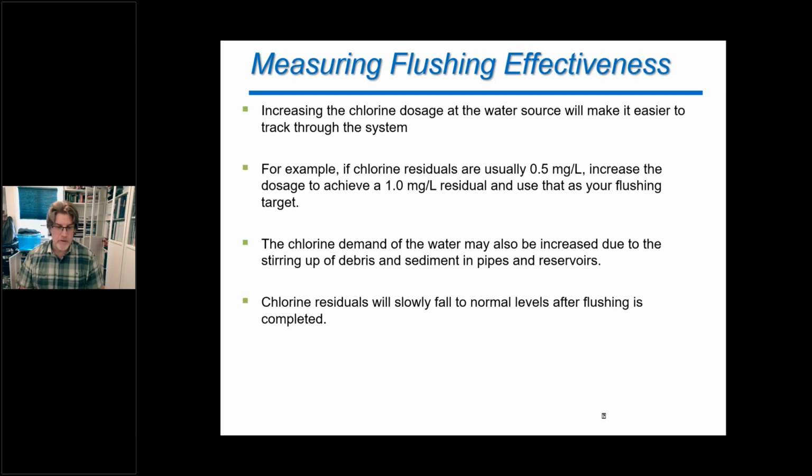And that's information you can put out to the consumers, saying, hey, while the flushing is happening, you're going to see a brief increase in the chlorine residual. And don't worry, after the flushing is done, you can turn the chlorine pump back to what it normally is set at. And that chlorine residual out in the system will slowly fall off. So you might just have a few days, a week where it might be a little bit high to help you with the flushing. But it'll drop off very, very quickly.